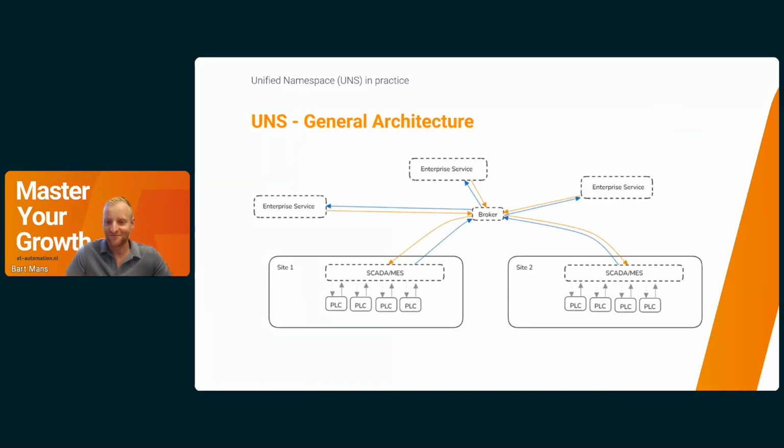This one. Two layers of MQTT connected. The MQTT broker, PLC. So the question is, can we connect the PLC directly to the MQTT broker? Yes, that's possible, and the same applies to the question that I just answered. If the PLC is able to communicate over MQTT, it's definitely possible. I use the SCADA MES here as a translator, but if the PLC is able to communicate with a broker, you don't need the SCADA MES system in between.